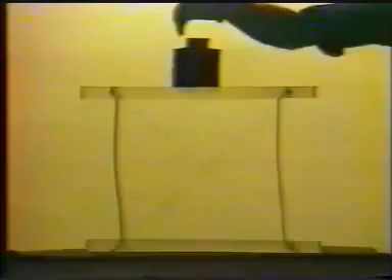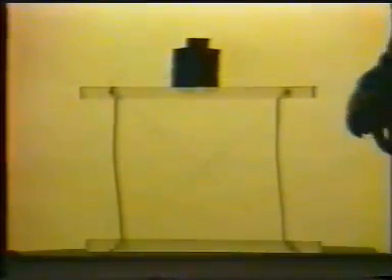In reality, the connection of the column to the beam will have a finite stiffness and will provide some end fixity to the column. In the extreme, if the beam is much larger, the column may have a fixed or encastre end condition. This condition can be seen in this model, in which the column ends are built in.